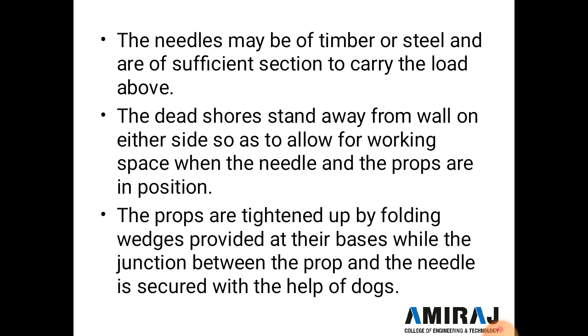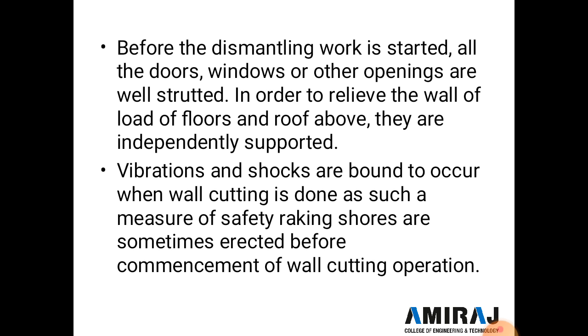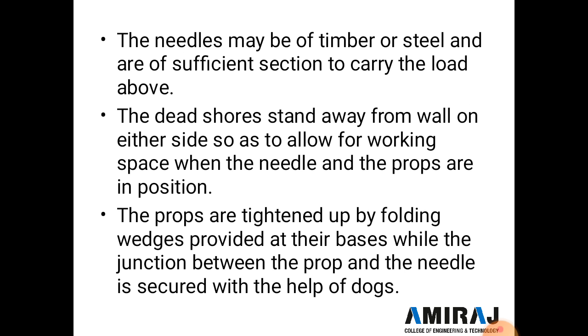And the props are tightened up by folding wedges provided at their bases, while the junction between the props and needles is secured with the help of dogs.